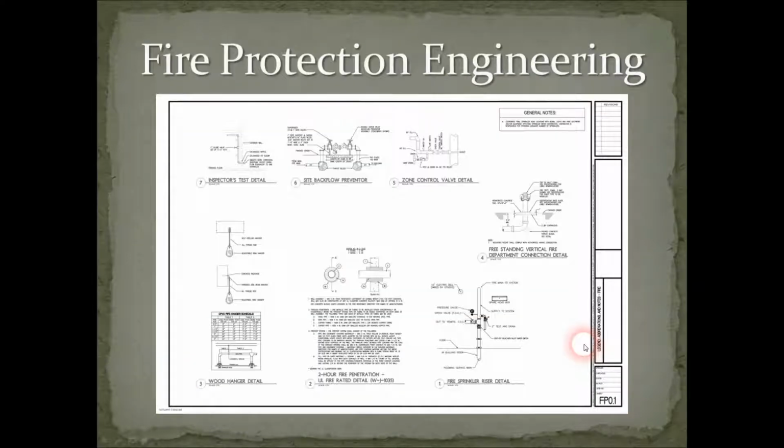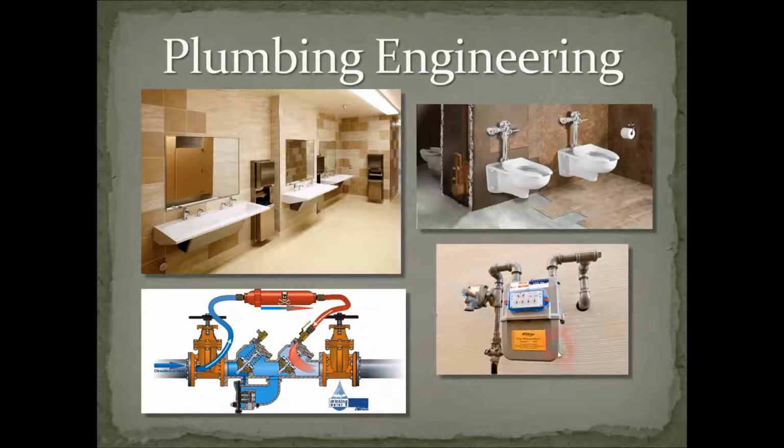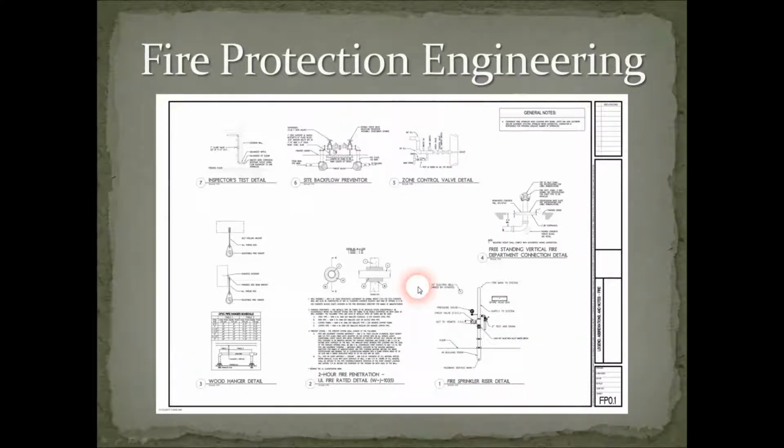This meter over here that you see, whoops, a little too far. This meter right here is a gas meter. Again, from the bottom, the gas comes from the city utility. It goes up, it goes through a regulator so that it has the correct amount of pressure, and then it goes from this pipe into the meter. This is the gas meter that the utility will read to know how much to charge the people for this building. And then it comes out of the meter and then into the building to serve things like furnaces, water heaters, gas ranges, and things of that nature.